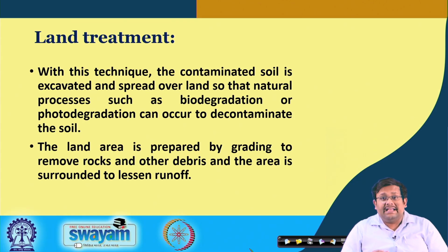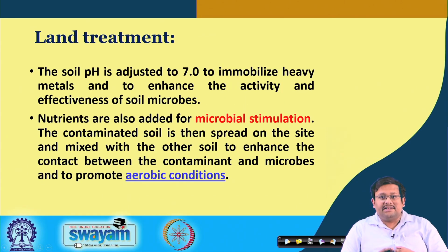Remember, the land area which is used for land treatment is prepared by grading to remove rocks and other debris, and the area is surrounded by a barrier to lessen the runoff, because if there is runoff, then there will be a chance of movement of contaminants from this contaminated soil to other areas where contamination is not present. So, this is about the land treatment. Let us move ahead and see the other aspects of land treatment.